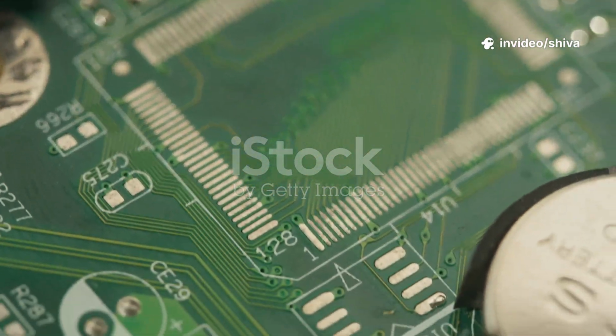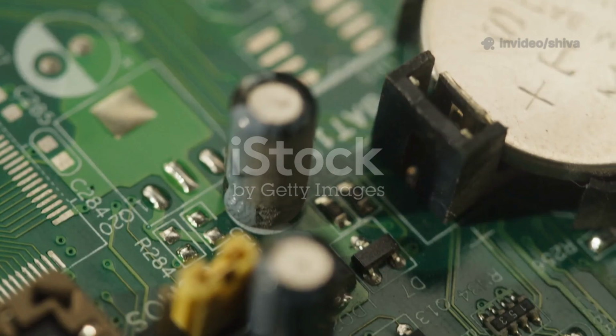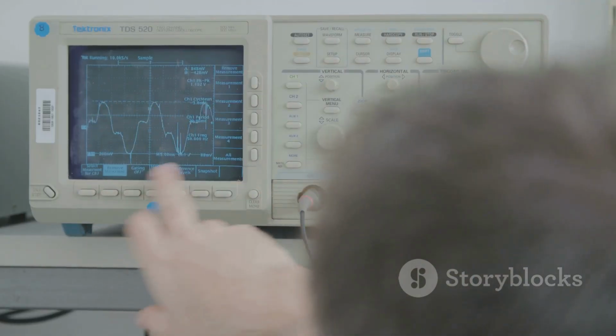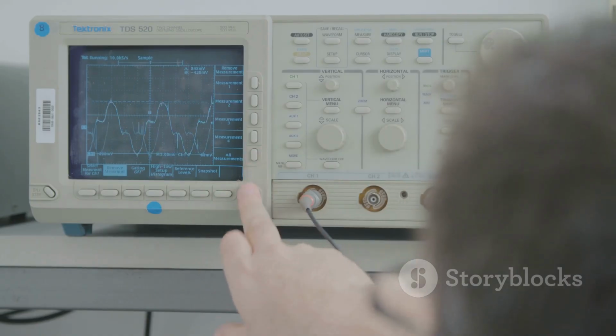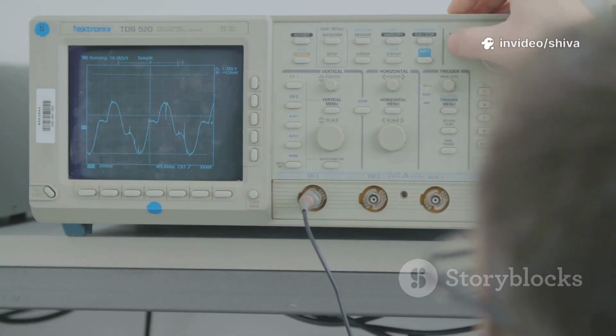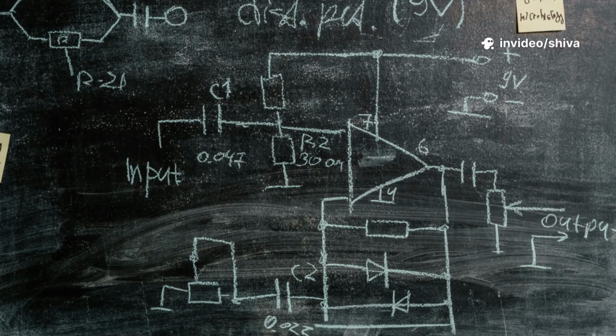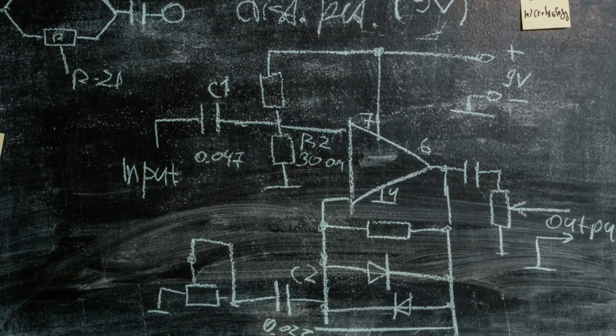It's made from one AND gate and another special gate called an XOR gate, which stands for exclusive OR. The XOR gate is like an OR gate, but it only outputs a 1 if one input or the other is 1, but not both. It's exclusive. A half adder takes two inputs, let's call them A and B, and gives two outputs, a sum and a carry.